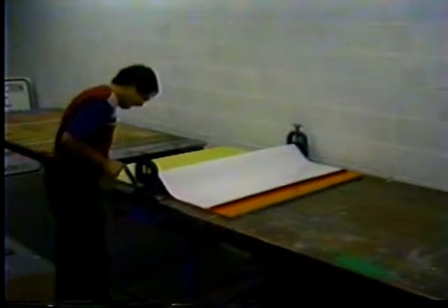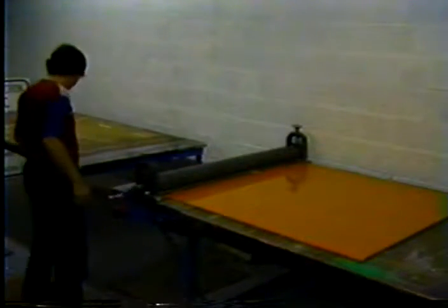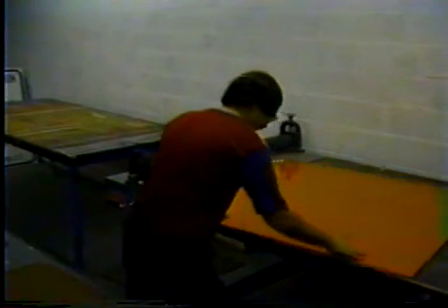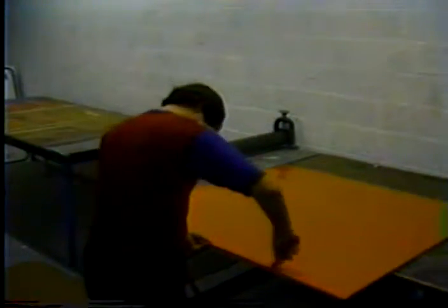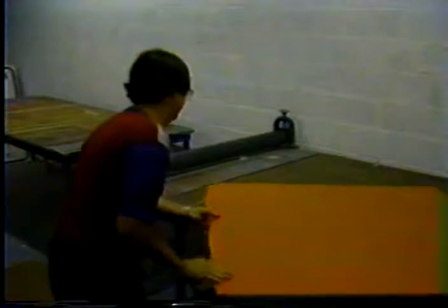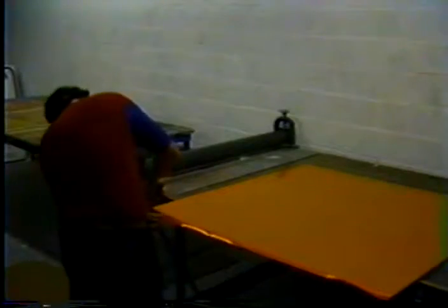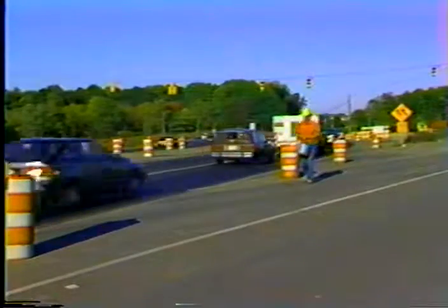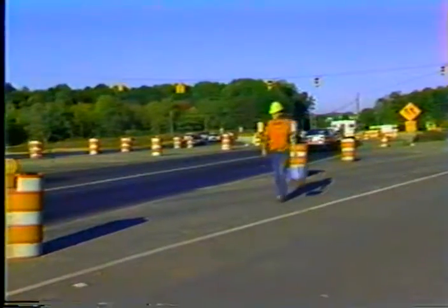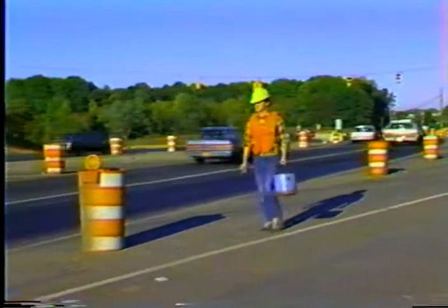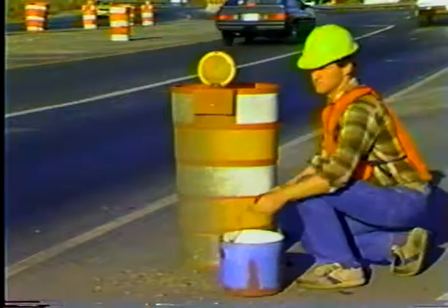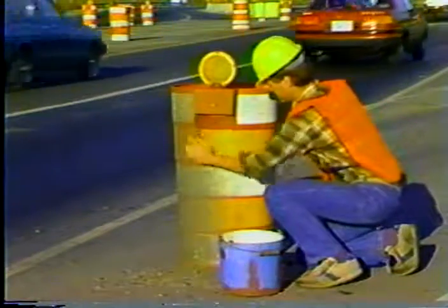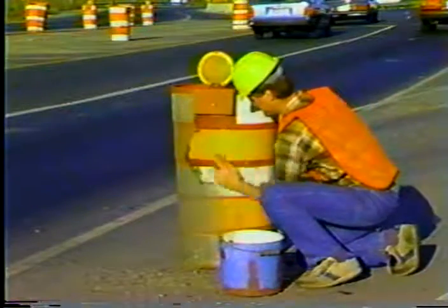All signs and channelizing devices that will be left on the road at night must use an approved grade of reflective sheeting to provide sufficient nighttime visibility. The condition of the sheeting largely determines the effectiveness of the device. Sheeting that is torn, peeling, cracked, or splattered with asphalt or concrete will not perform well under the best conditions, but it's particularly bad at night. Routine cleaning and replacement of signs and channelizing devices should be encouraged, if not required outright by the plans. Construction dust alone can diminish brightness by 50%. Worn out or damaged sheeting will reduce it even more.